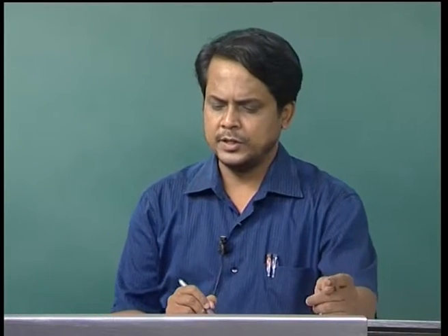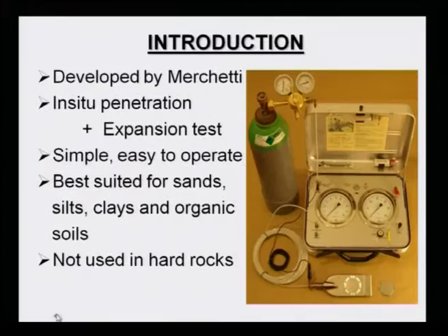Next is your dilatometer test. The dilatometer test has been developed by Marchetti. It is basically an in situ penetration as well as expansion test. It is simple and easy to operate. So, best suited for sand, silt, clay and organic soils. It has not been used for hard rock.